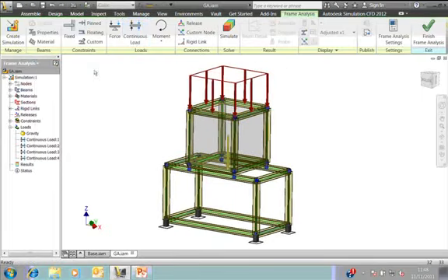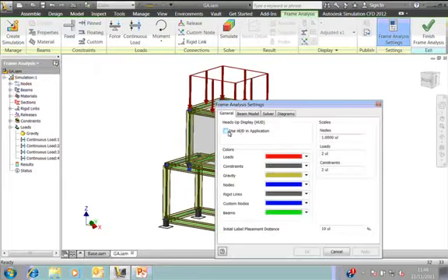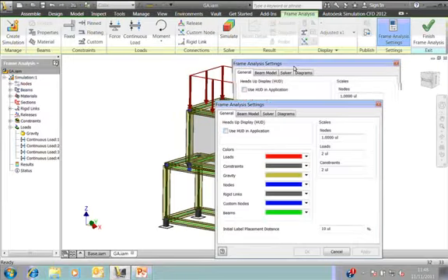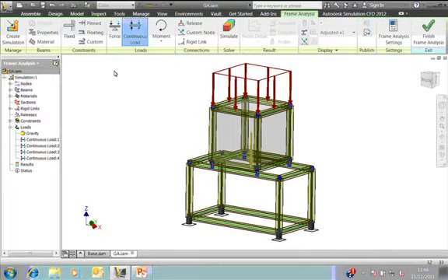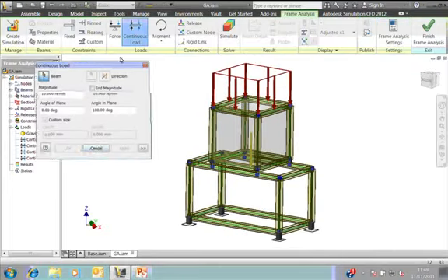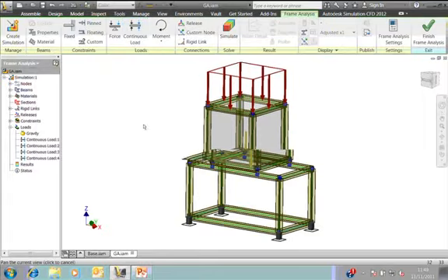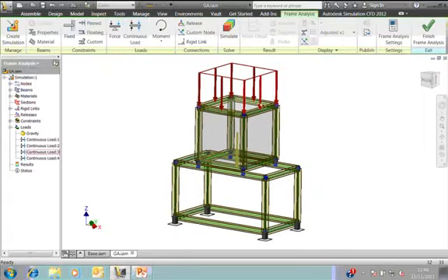It's a lot quicker doing this with dialog boxes, so in the frame analysis settings, it's a good idea to take off the heads-up display tick box. That gives you a better and easier way of working by bringing up the dialog boxes instead on the software. Okay, so we've now got our loads, we've now got our constraints, the gravity's in the right place. Let's go and simulate this.